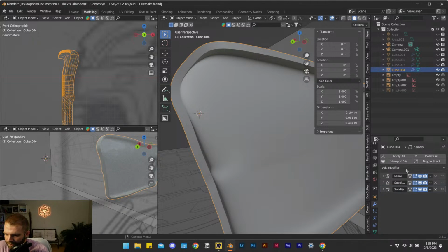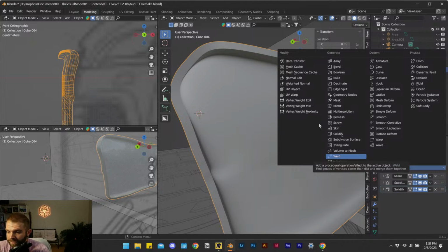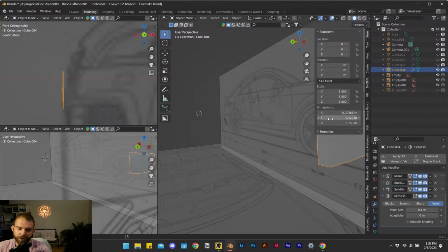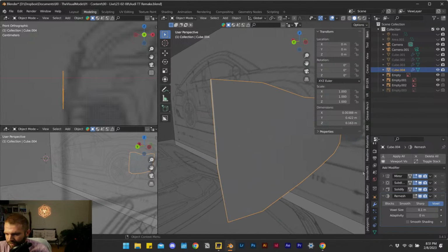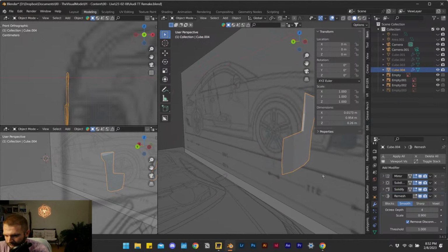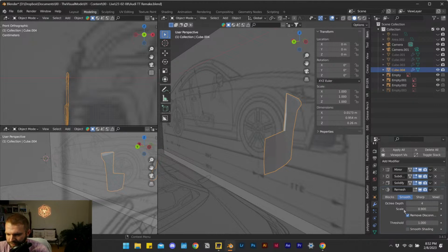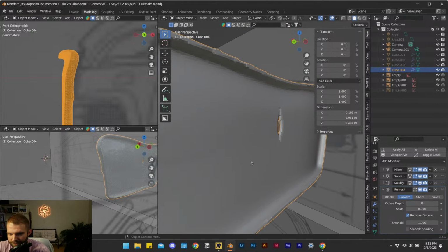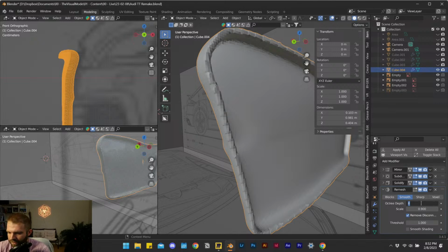So as I was saying, in order to get the topology really cleaned up, you can always use the remesh tool. I think this comes in really useful, especially when you're importing geometries from other places. We can just grab the remesh tool, and we can choose whether it's a smooth object, a sharp object, or a voxel. I find that octree depth set to 8 or 9 might be slow at first to calculate. But there you can see it starts to rebuild it. We can hit 9 to get closer to the real shape.